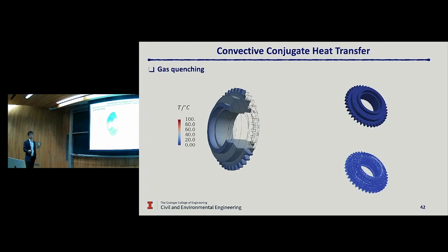of the temperature compatibility and the flux compatibility during the simulation. All of them are reduced to a very low level. So we feel that this approach can be applied to many interface-coupled multiphysics problems as long as there is a Neumann boundary condition that involves a large property ratio, where the interface couldn't be exactly captured, and you still want to have a high accuracy to enforce the boundary condition. This method can be applied.